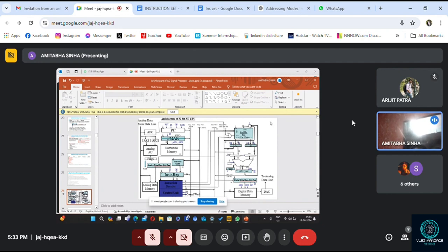After that, when your design is settled and finally you are going to implement, then you have to decide what technology you will be using, what submicron technology will be used. That depends on the complexity of the overall circuitry, analog, digital. Then what is the maximum speed it can handle, and from that the timing will be coming. Now for this timing, whether that technology can permit or not, that again depends on many other things.